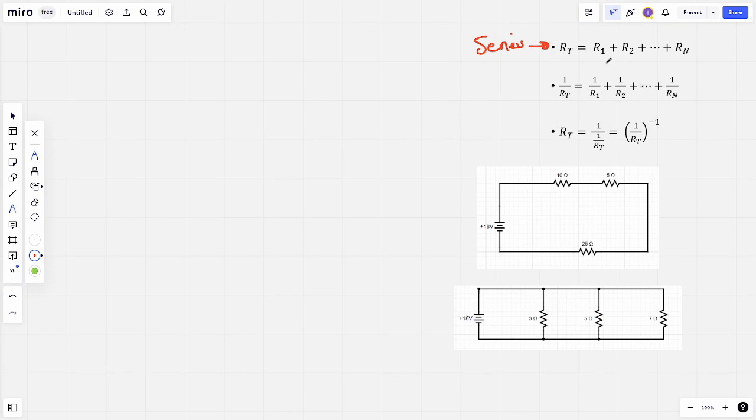So, what does that mean? If we look at this diagram below, this is a series circuit. We've got 3 resistors, so if we say 10 ohms is R1, we've got 5 ohms as R2 and 25 ohms as R3. Now if you imagine plugging in R1, R2 and R3 into the RT equation, what does the total resistance look like? So let's do that.